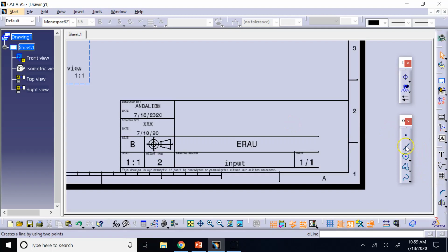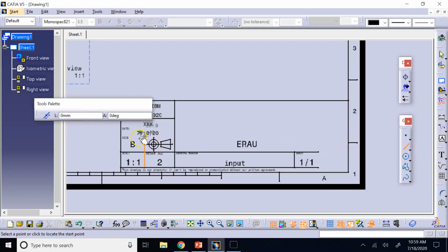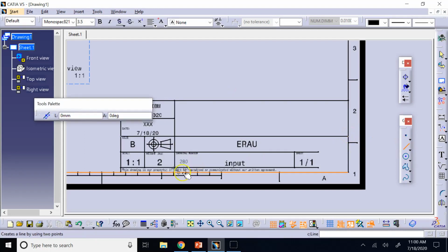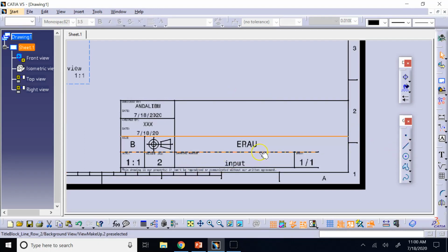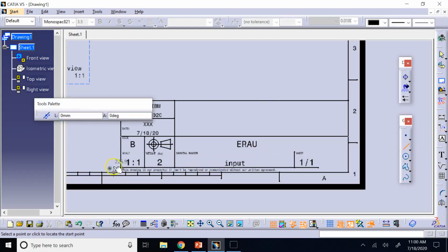That's your toolbar here. Okay, so if you don't like this, you can just eliminate it and then go ahead and draw a line like this, right? And you can do the same thing here. So feel free to modify this table in any way that you want. And you see here it jumps from grid point to grid point. So if you turn snap to grid off, then you can arbitrarily click wherever you want.